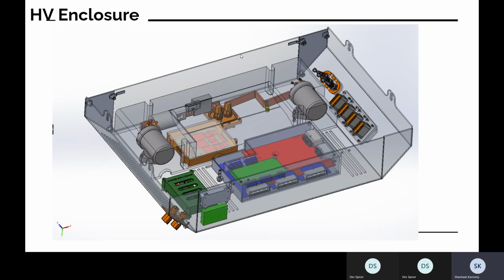In the battery pack, though, we have a couple of items. We have the accumulator management system, which, as I said before but maybe didn't explain completely, takes all the voltage signals from across the battery pack, all the thermistor signals, and turns that into CAN bus, which is a digital signaling protocol. All the thermistor and voltage signals are analog, right?